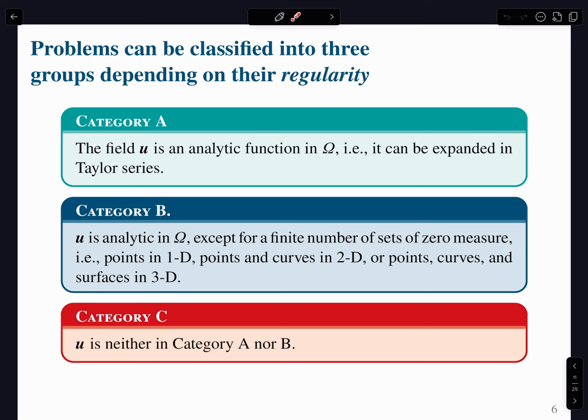For instance, I can immediately think of a problem where if you try to model the so-called Flamant problem, which is basically a semi-infinite space, and then you just place a concentrated load on the top. As you refine your mesh, your strain energy keeps increasing, and so at some point you have to do something to get some sort of finite strain energy, right?